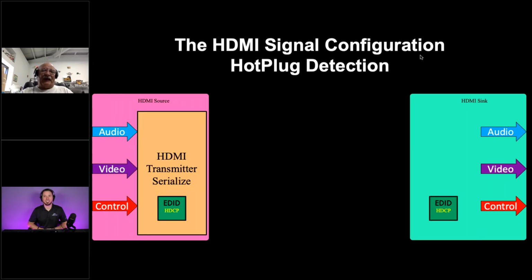Okay, well that's what happens when people put these 5 volt lines on, because they literally put them on in parallel with the 5 volt line. So now you plug it into a little 5 volt wall wart, like a USB wall wart or something like that, and that's okay. But if that wall wart decides to go north, for say 6, 7, 8 volts, it'll backfeed back into the source and kill it. Zap. That's bad.